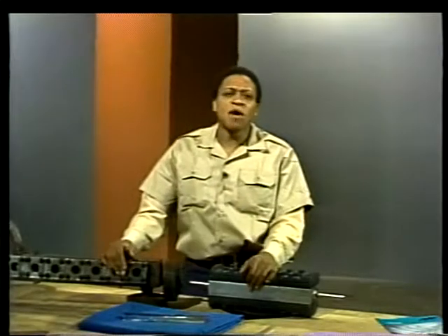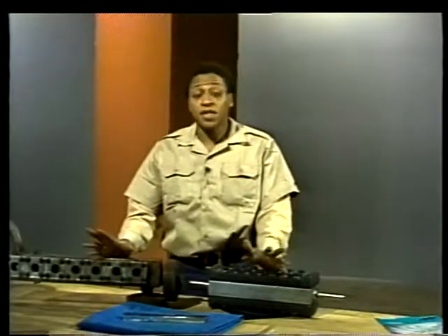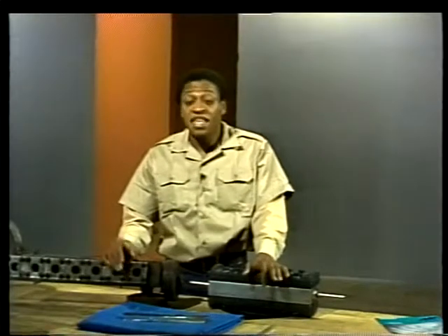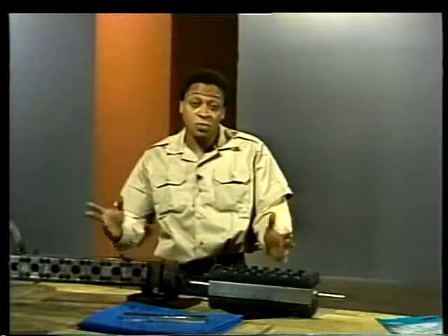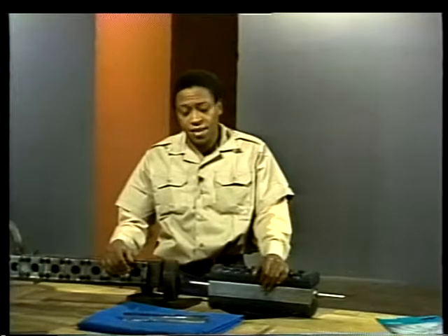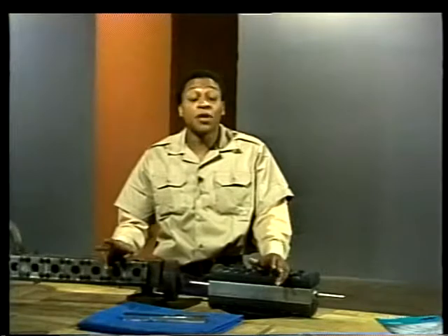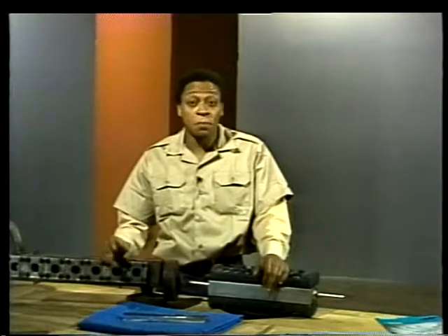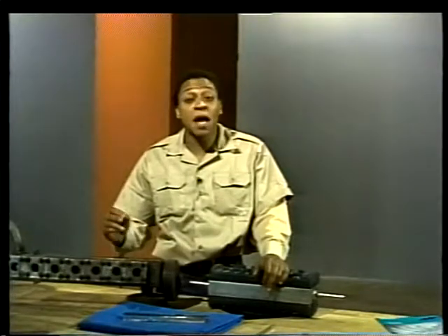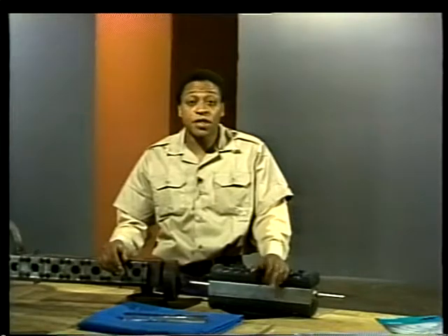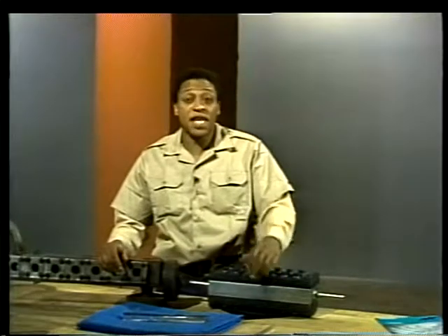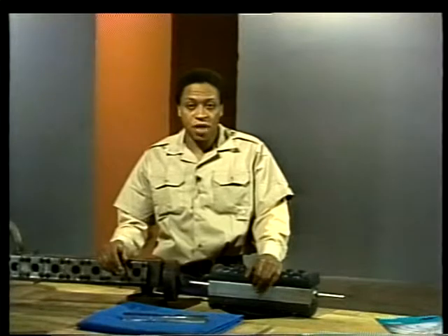The dirt or silt often comes from inside the tank or vessel where the gauge is attached. Even the cleanest vessel usually has some stuff in it that can cloud a gauge glass. When deposits form on the inside of the glass, there is a maintenance problem. Sometimes opaque glass can be corrected by blowdown. If it isn't corrected, or if there is a chemical attack, the glass must be replaced.